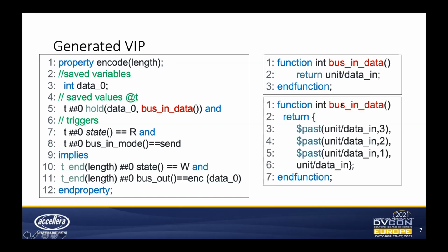So let's say the data is received sequentially and we receive 8-bit packages over 4 cycles. This is, in our experience, a pretty common thing that happens, that you have sequential transmissions in the RTL, whereas in the abstract model, we just want to say, okay, give me the data. I want 32 bits. I don't want to have 4 events triggering for that, because that will cost me simulation time and will make my whole simulation more complex.